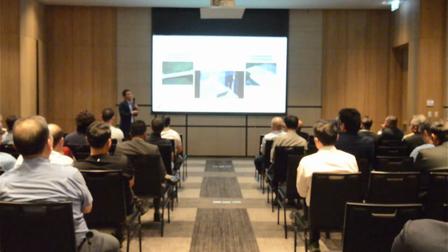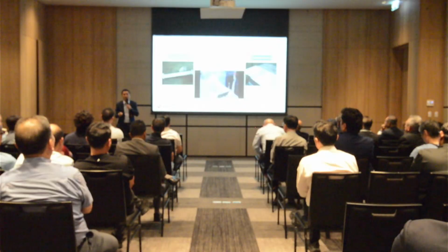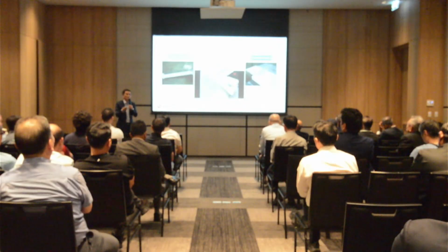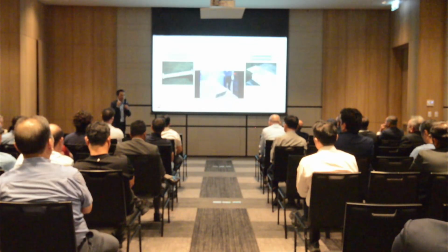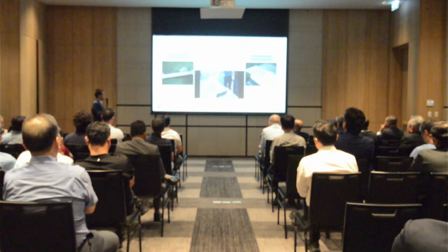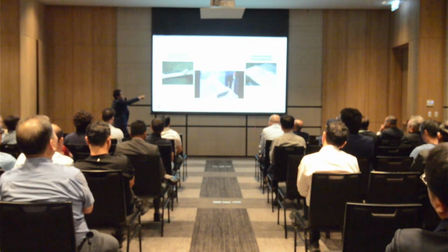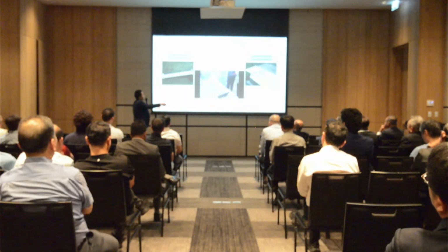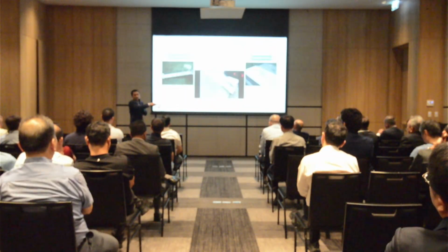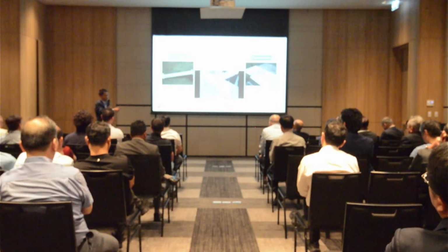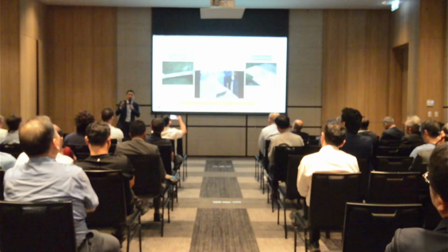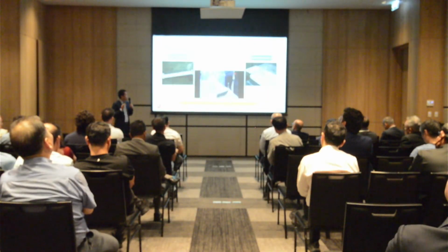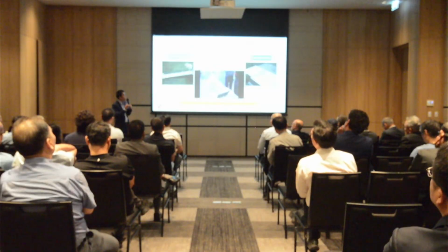Because we are higher than liquidus, we have no limitation on the alloy. Any kind of alloy you can make, no matter 6000 alloy, even pure aluminum, eutectic alloy, aluminum silicon 12, or 6063 or 7075. That's why there's no limitation on alloy. You can see the flow behavior is different. When you continue cooling down, it's like a semi-solid. This is 356 alloy. It's about 50% solid fraction. That means the GISS process can make any solid fraction of semi-solid slurry by cooling speed and time control.